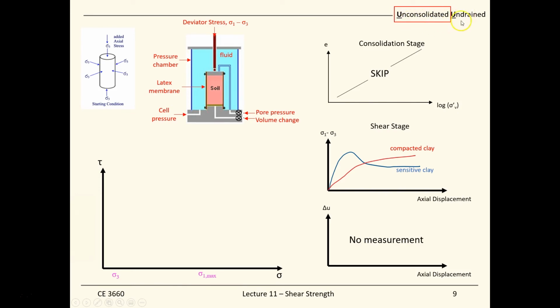And then after you apply the cell pressure, you conduct the triaxial test, the consolidated undrained test, and you will get the stress strain curve. From the stress strain curve, you know the maximum deviator stress, and since sigma 3 is a constant, you can calculate the sigma 1. From the maximum stress, you have the sigma 1 maximum. Then you can plot the Mohr circles to represent the failure conditions of the soil samples, formed by sigma 3 and sigma 1 max.